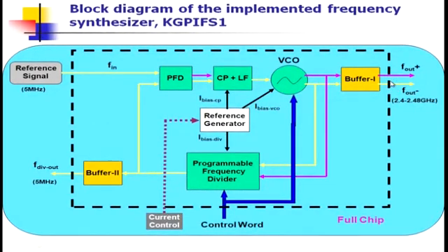You need two such pairs of that to find out this frequency. You need a buffer to isolate the free running VCO frequency from the loading from outside. And whenever I want to see the programmable divider output, you need a buffer, and this is the division output, 5 megahertz. So, make these two blocks in your chip, and these controlled blocks are a departure from the conventional design approach, to avoid the loading.